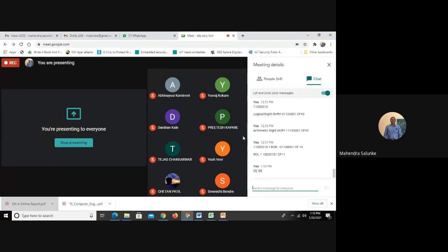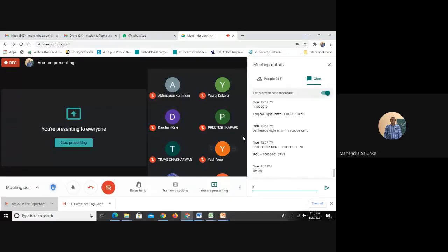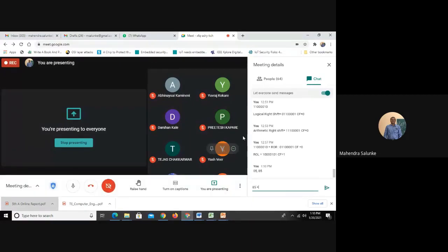Now, if I change the statement, and tell you that these two numbers are signed numbers, in that case, which is the bigger one? 05 will be the bigger one. How? Because 05 is a positive number and 85 is a negative number. How is 85 negative? If I put it in binary, both numbers are hex numbers, so that is another condition that everyone should keep in mind.